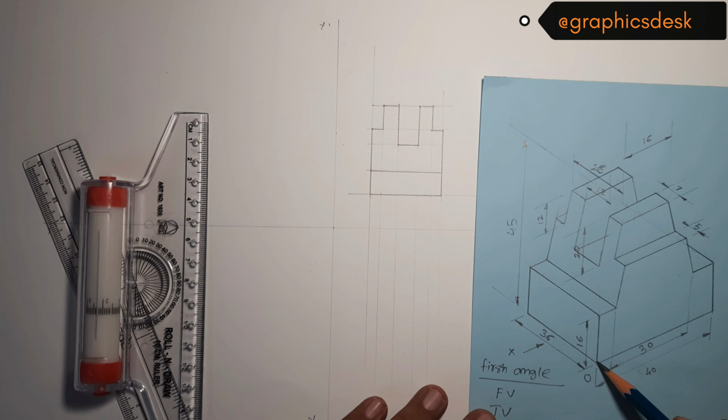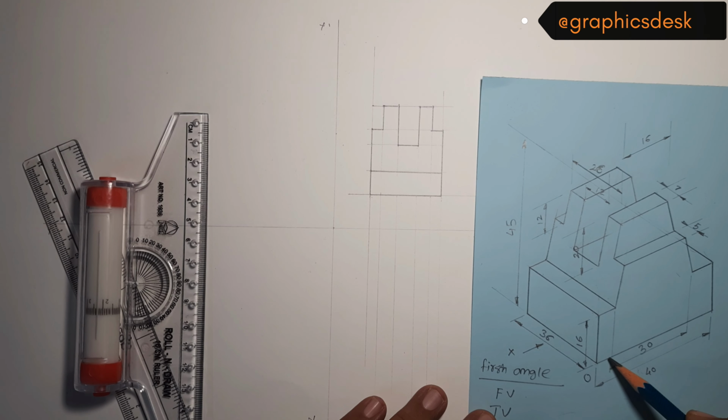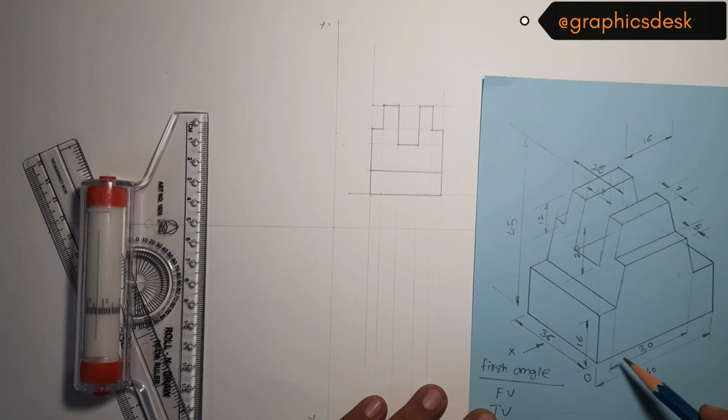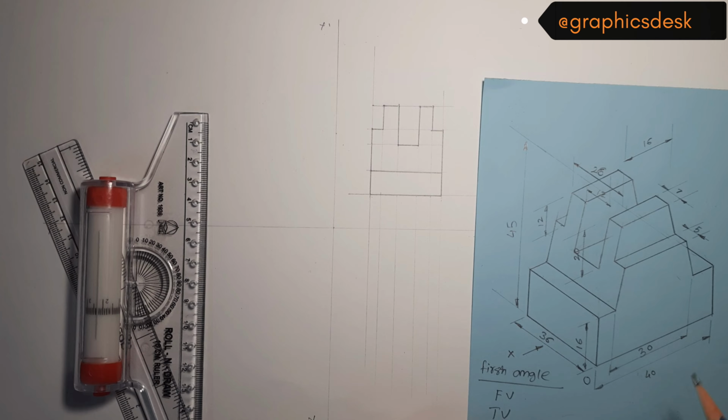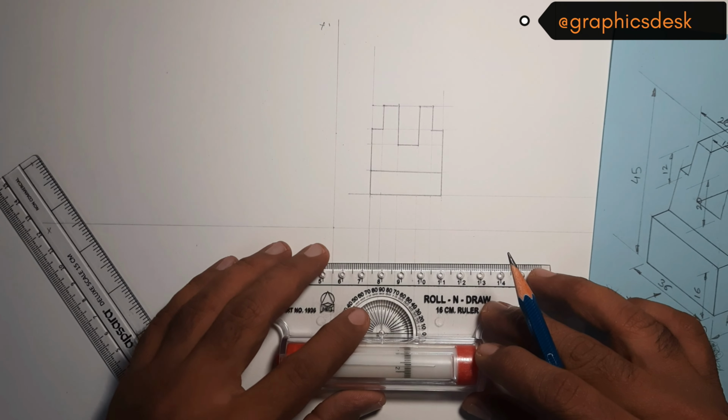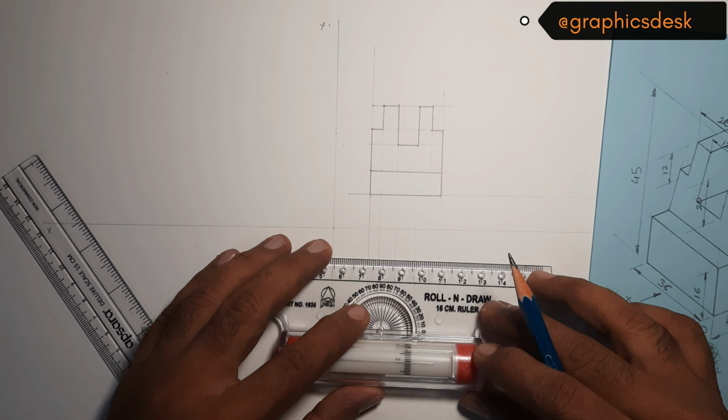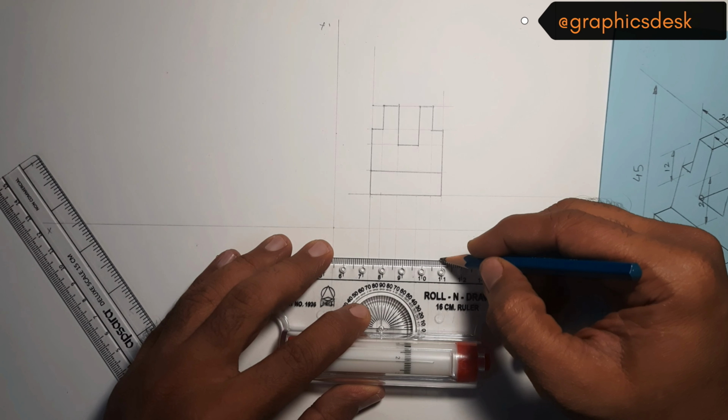So what we'll have is a rectangle, which is again a solid line first. We'll have to measure 40 mm in this direction, which will essentially be the height if we talk about the top view, and 36 mm is already given to us by projection. So let me start with the line over here, and then let me complete the rectangle as 40 mm measuring from that.